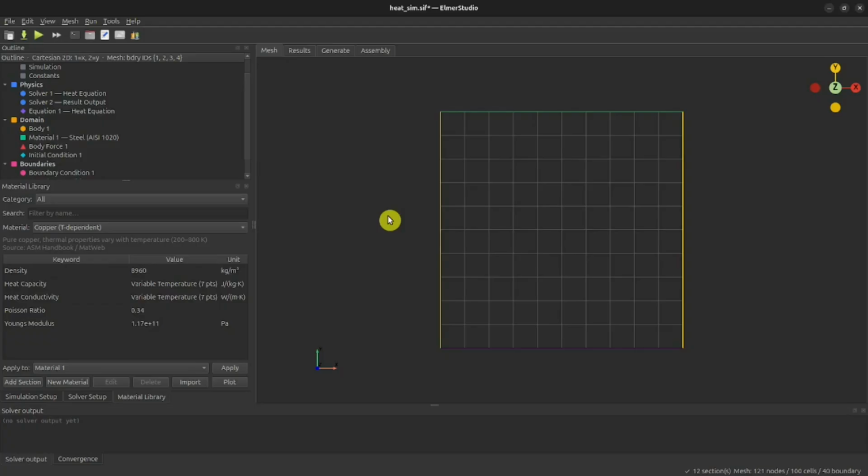Now, that's obviously deliberate. In Elmer's heat solver, an edge with no boundary condition block referencing it gets the natural boundary condition by default, which for heat conduction is 0 flux, insulated. You get insulation by writing nothing at all, basically. The empty space is the boundary condition itself, so it has a meaning, and that's why it was not identified.